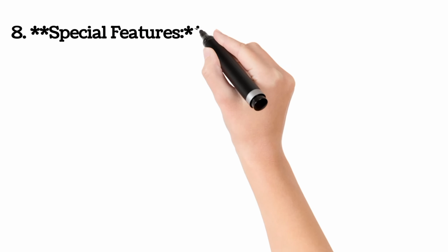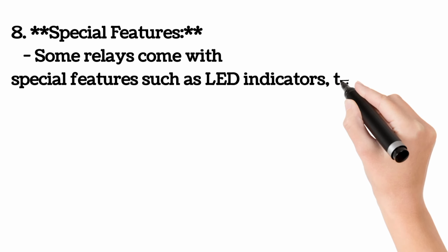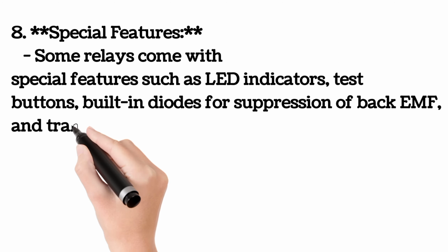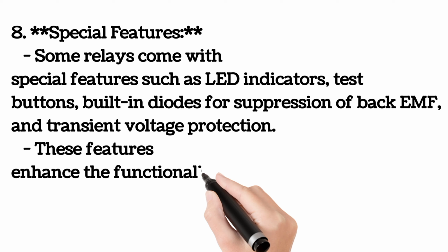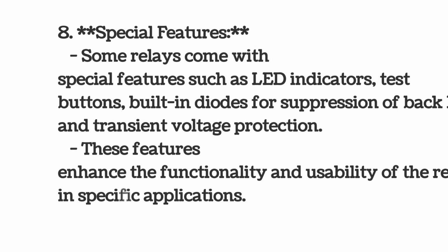8. Special features. Some relays come with special features such as LED indicators, test buttons, built-in diodes for suppression of back EMF, and transient voltage protection. These features enhance the functionality and usability of the relay in specific applications.